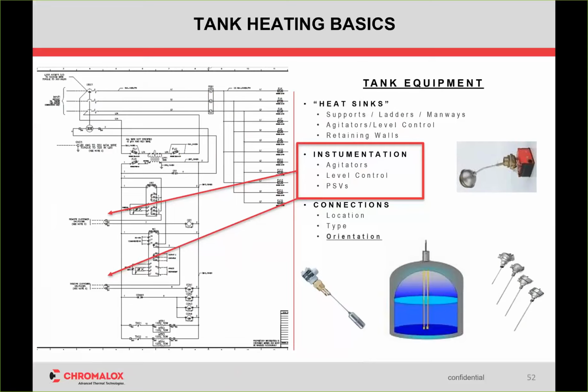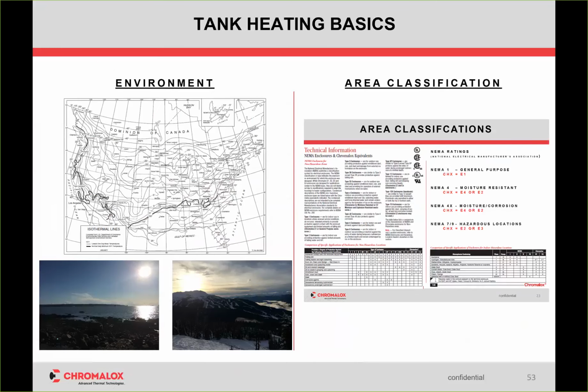But specific to tank heating, they could either be an obstruction that you're trying to design around, or something that they want to include in the control of the heater. We always say we don't want the heaters to be exposed or open to air or the level to go below the heater. There's level control right there, right? So just an important thing to point out.